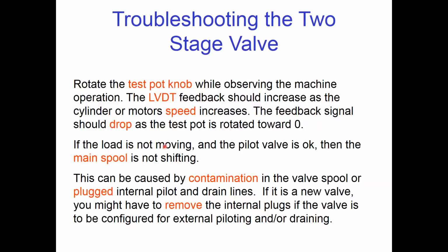If the load is not moving and the pilot valve is okay, obviously the main spool is not shifting. Now this could be caused by contamination in the valve spool, or you could have something plugged in the internal pilot and drain lines. If it's a brand new valve, make sure those pilot plugs are configured the way they need to be.